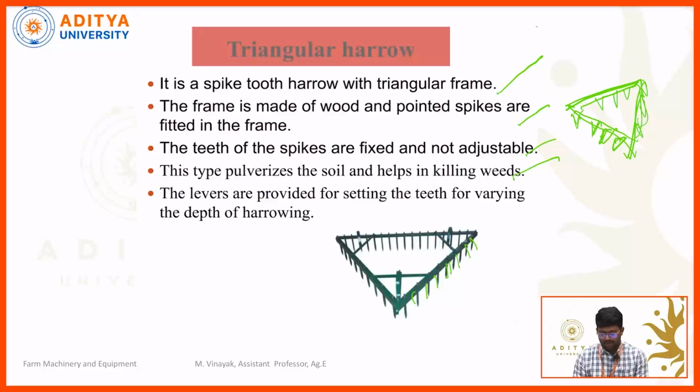The levelers are provided for setting the teeth for varying the depth of operation. So based on our requirement, the teeth size will be adjustable. If you want more depth of operation, you can change the tooth length.